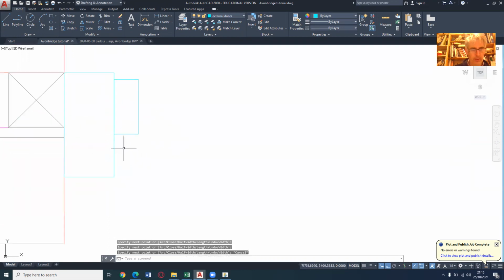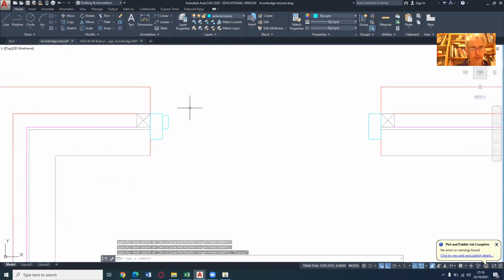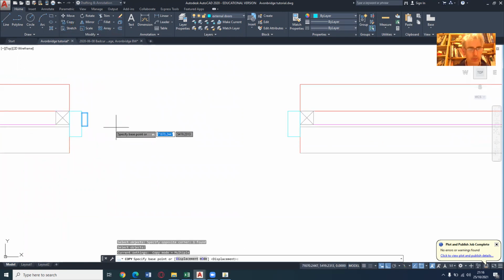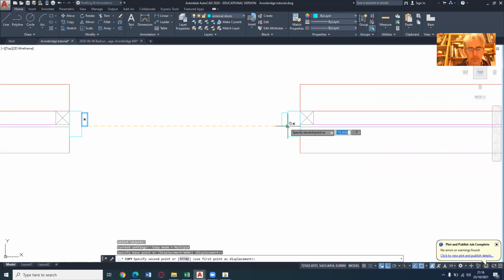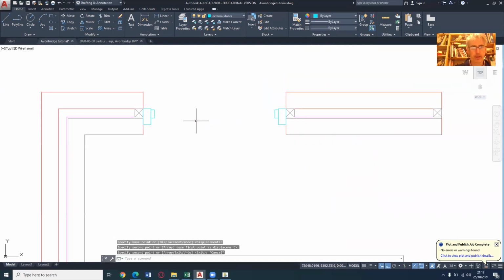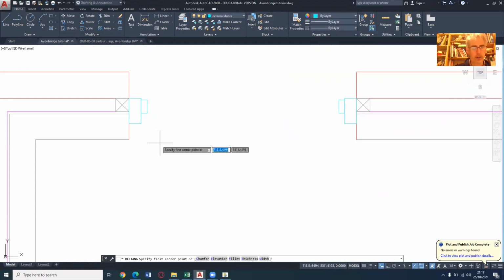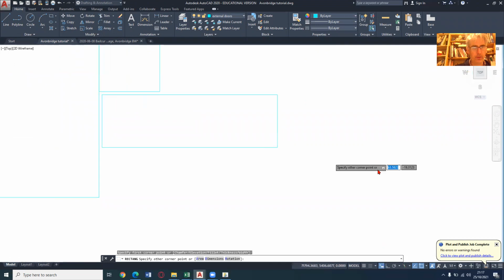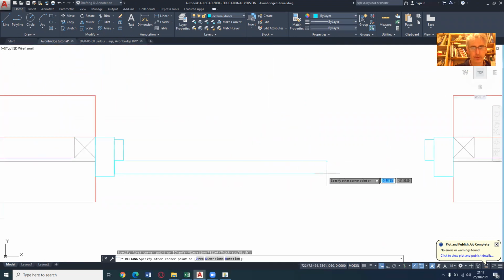Okay, so really our door thickness is going to sit in here, if you like. Just going to copy that across to the other side, making sure you use your snap points, hit escape, and then you've got a frame and a door stop. So in other words, our door is going to fit in here. Here's where our door is going to fit in.